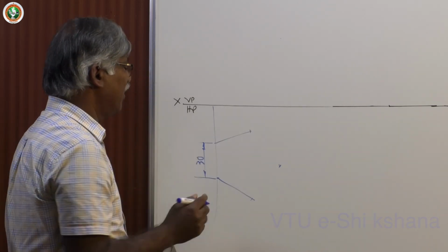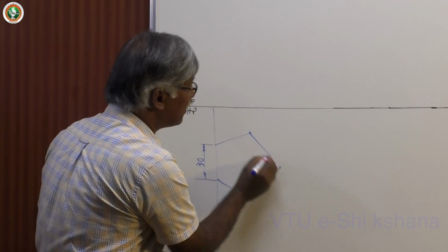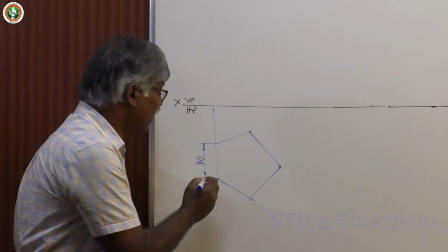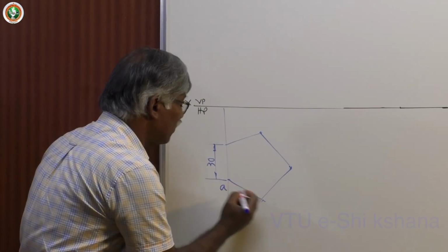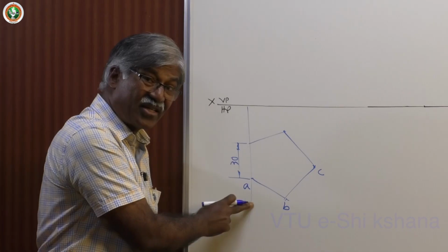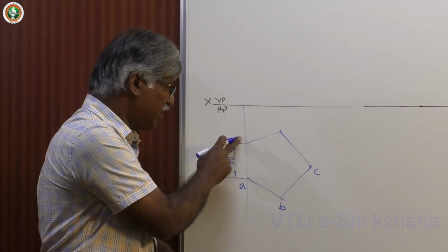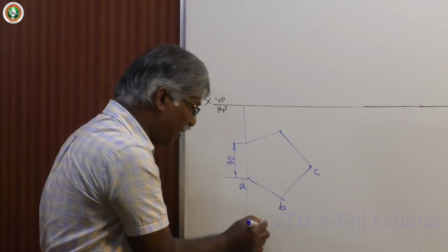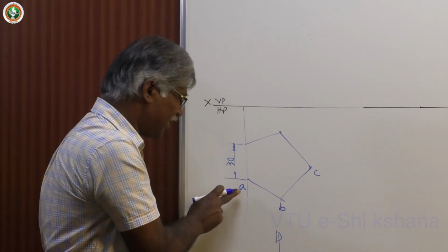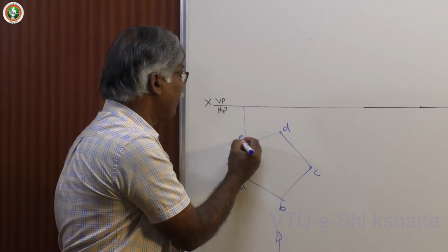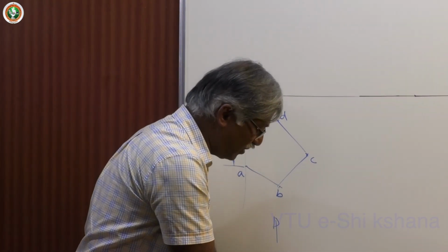Should take this and then draw. Then join this. So this is nothing but the top view. This is A, B, C, D. Please observe, I have started from the left extreme nearest corner, not this or this. Always visible points first. Left extreme nearest corner, I am here. So left extreme nearest corner is this A, B, C, D. Then dark this portion.